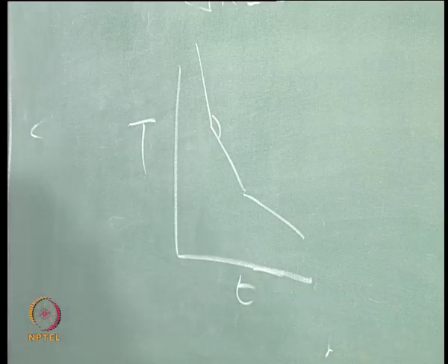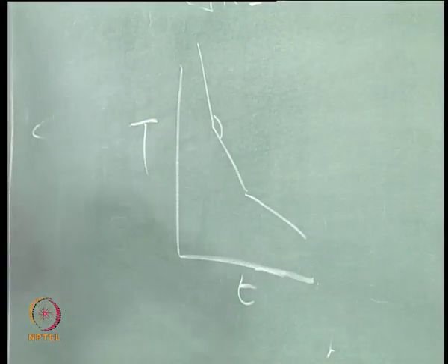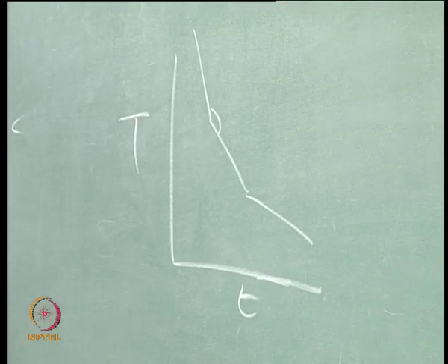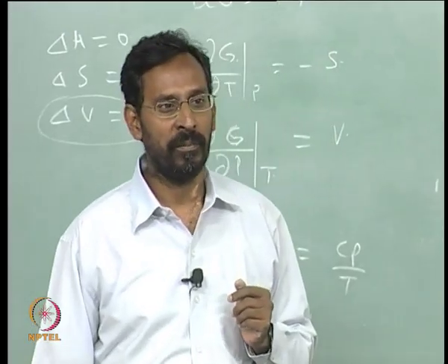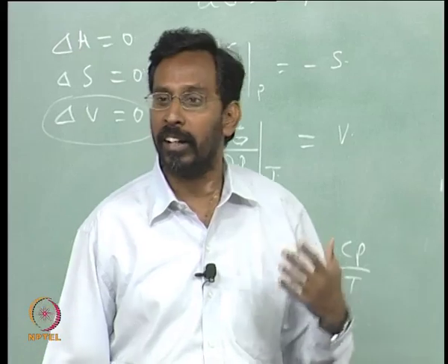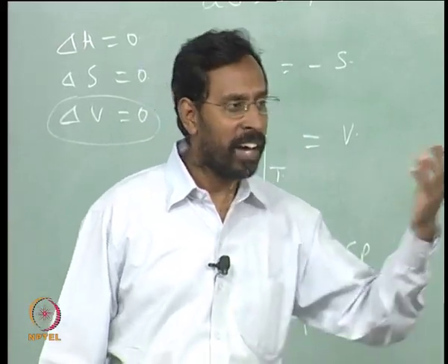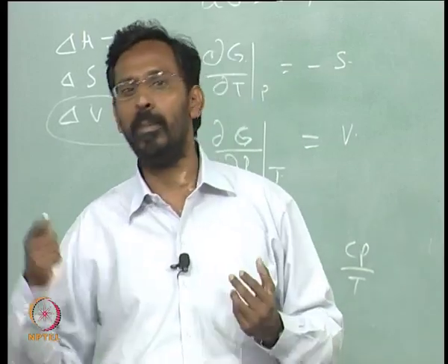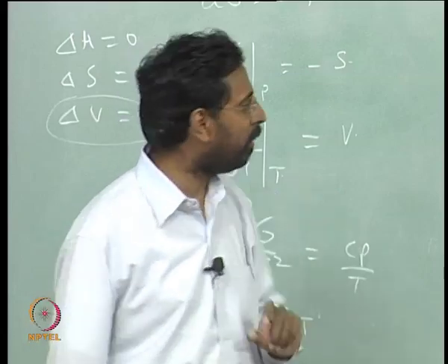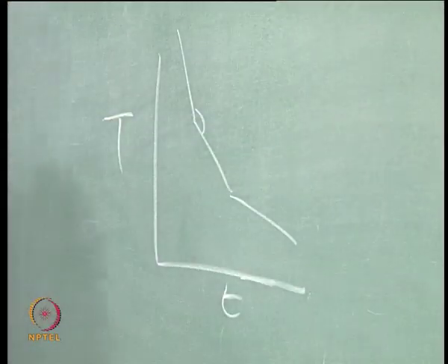So a typical cooling curve, that is why normal thermal analysis we do not use to simply find out solid state transformations. That is why we use what is called differential thermal analysis, because we are looking at the difference between a reference and a sample, where the reference does not undergo any transition at the temperature, whereas the sample is undergoing one. Because of the differences we observe, you start seeing the peaks.